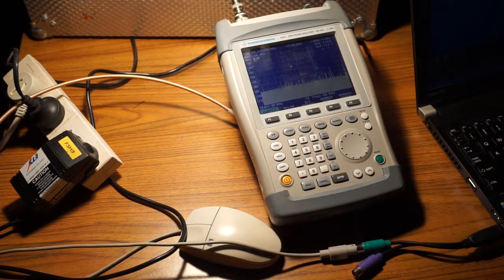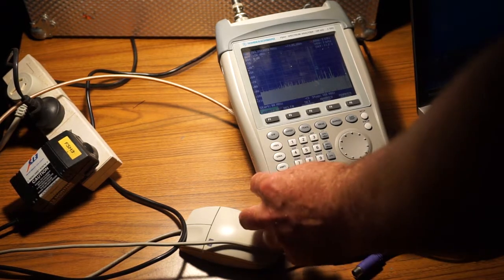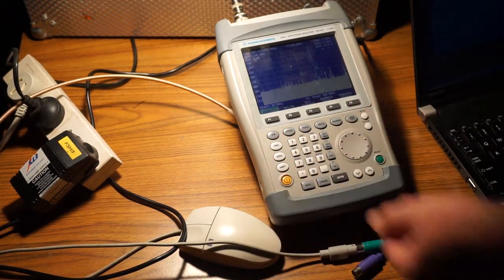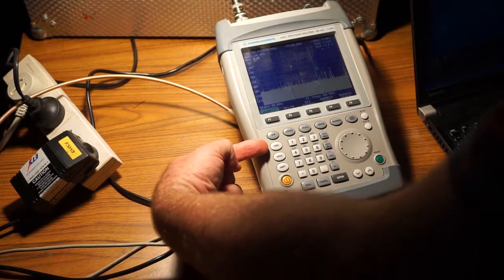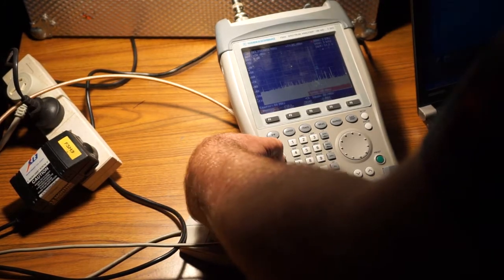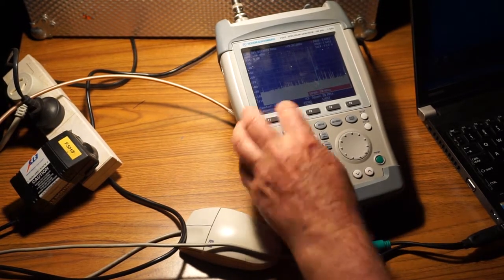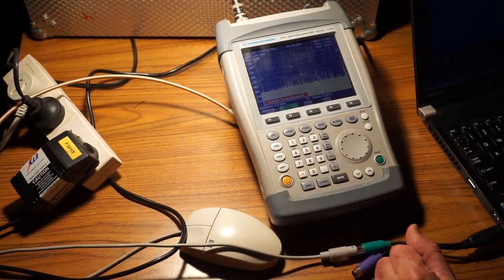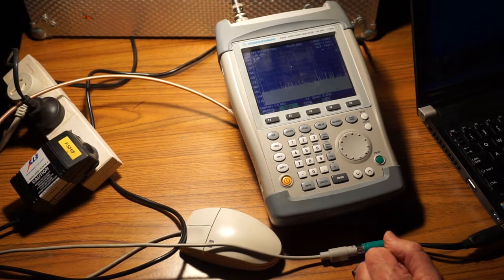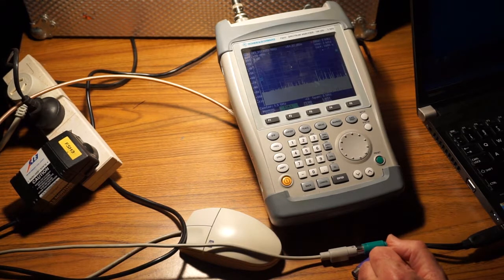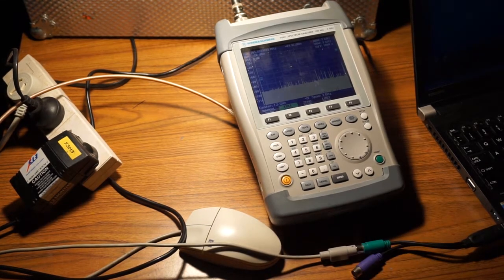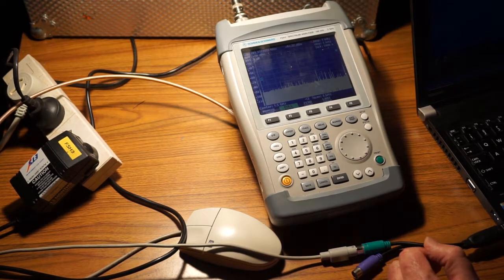So that's just a very brief rundown of it. We've had a look at the switches on the side, the frequency switch, the span switch. With the span switch, we can go to things like full span. With full span, that's now sweeping from 100 kilohertz to 3 gigahertz, and you can see what's happening on 40 metres tonight. We could have listened on 40 metres tonight, but with this antenna and all the other rubbish around, probably wouldn't be able to see too much.